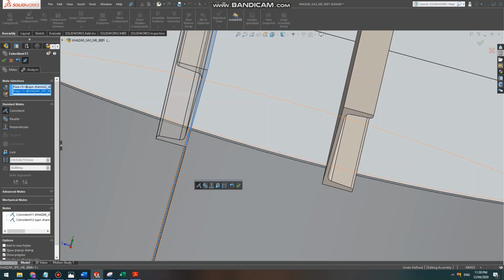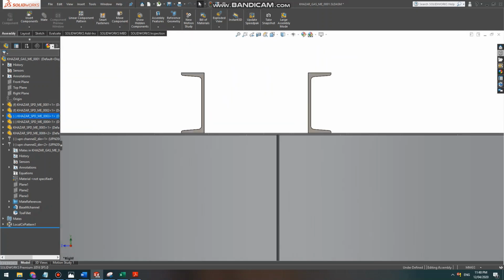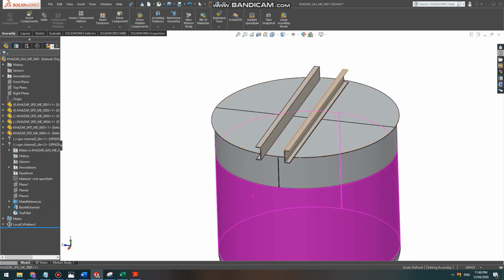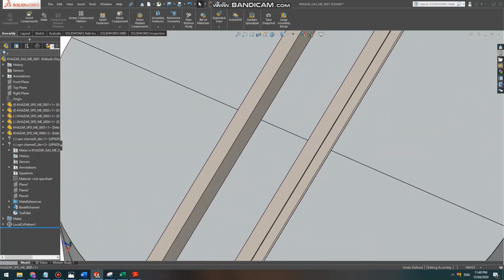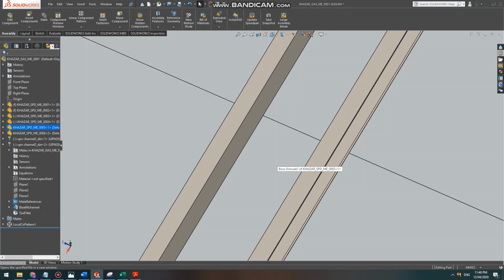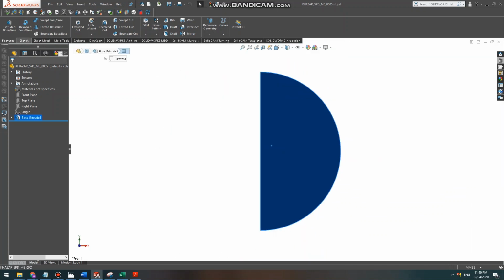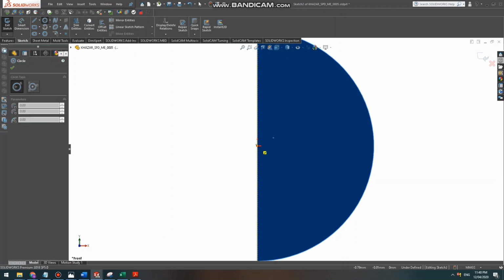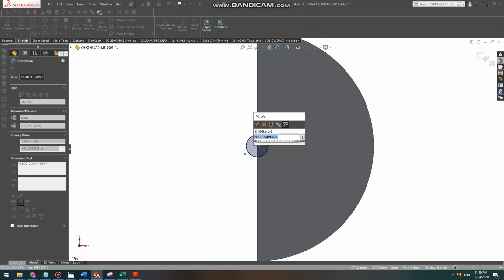Oops, it went the other direction. We don't want it to happen. We just do the following: we look at it like this and move it. So let's accept it as the middle of it, the center of the circle. However, we need to make a hole here, a hole by which we can install the mixer. So that hole will help us to dimensionalize the other stuff. So I have already did some calculations for the mixer shaft, and it's gonna be something like 80 millimeters of diameter for shaft, but we are going to install a bearing casing here, so the bearing casing diameter would be 500 millimeters.